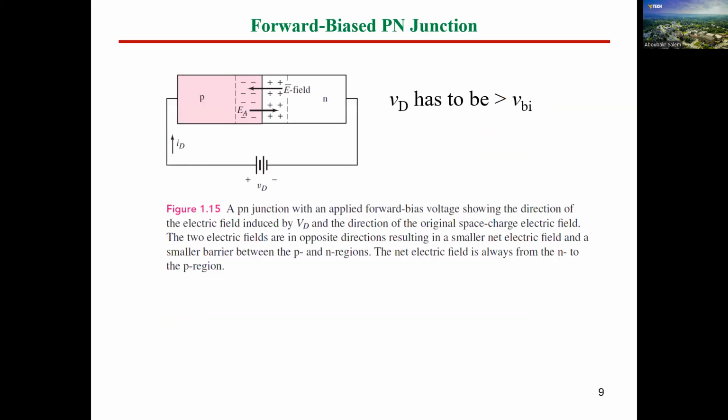And here we mentioned how to operate or start moving electrons through the junction. We mentioned that the volt has to be greater than the barrier. And we mentioned that the barrier, according to the semiconductor material, could be 0.4 volt to 0.8 volt, for instance. And we will see that, guys, in some data sheets of some power or electronics components based on the PN junction.